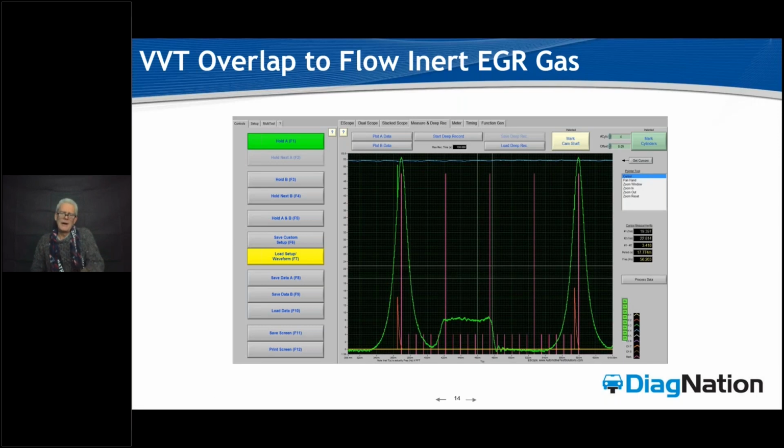Here at the bottom of this pocket right here is where we're going to check exhaust camshaft timing. Now, when it comes to variable valve timing, this is an incredibly important baseline tool to understand what's going on with those cam phasers when they're being commanded on and off. And this is a great way to find valve leakage creating intermittent misfires, as well as cam timing problems.